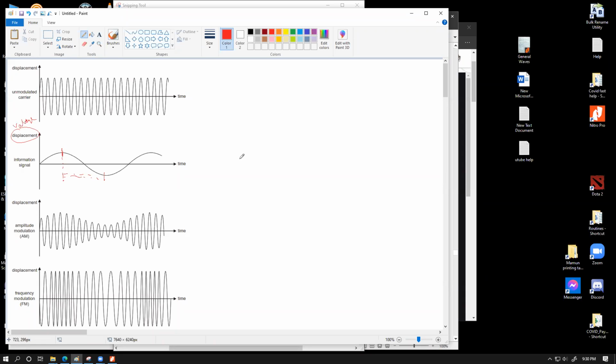It's voltage versus time. So if you talk into a piezoelectric crystal, or a microphone, which is basically a piezoelectric crystal, and you place a tuning fork in front of it, that tuning fork will register a voltage variation like this. Without the vibration, there'll be 0 voltage. When there is compression, it's going to have some positive voltage. Whenever it's under rarefaction, it's going to give us some negative voltage. So that's why I'm writing the term voltage over here.